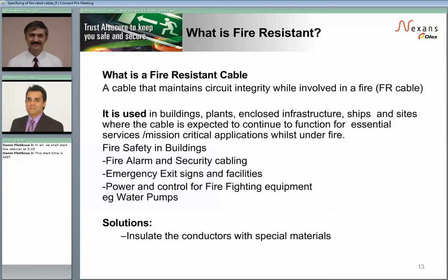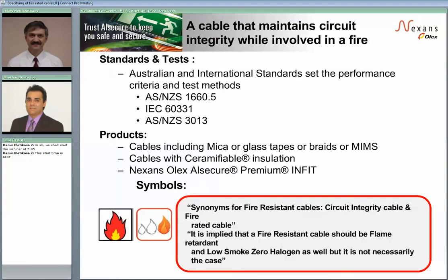Now, it's not like the earlier standards which address the cable itself or the properties of the materials used in cables. The AS/NZS 3013 is for the testing and classification of elements in a wiring system so that the whole system may perform as required. The testing takes place one element at a time, but the key criteria is that the furnace is controlled so as to follow a specified time temperature curve. I understand this curve attempts to represent a typical fire in a building with a mixture of burnable materials.